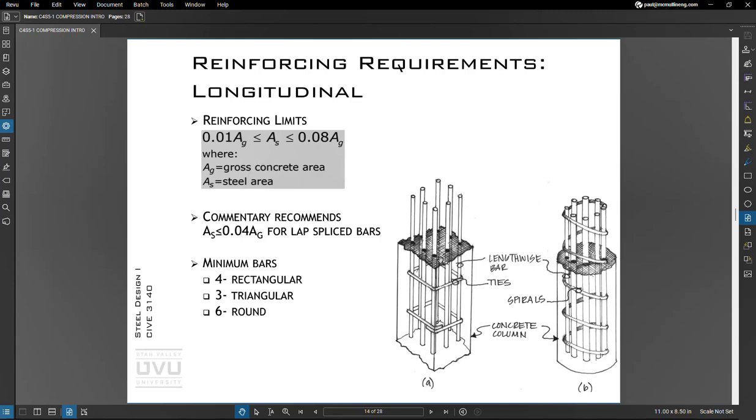So generally, if you take your area of concrete, multiply it by somewhere between 0.01 and 0.04, that's a good starting place for the amount of reinforcing. Or maybe said a better way, once you do your concrete column design, if you check this economic or functional limit, it's a good way to say this is a column that's buildable and is fairly economical.